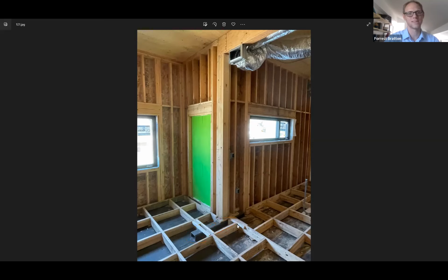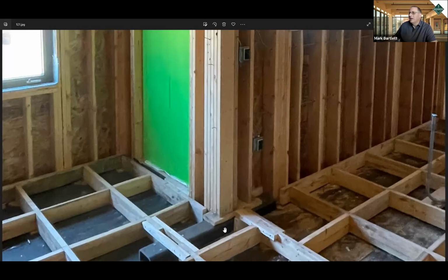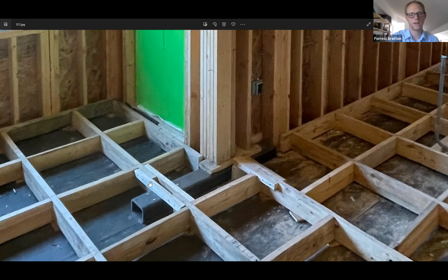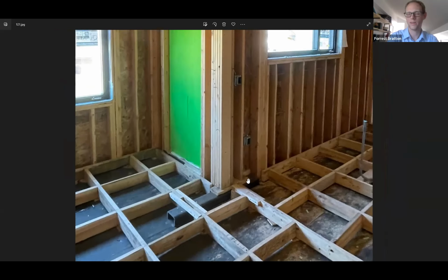We can't do this. One of the things I noticed in this image I've pulled up here, you've got basically a beam spanning across an opening, and obviously a multi-wide column coming down, and then you've got additional steel to distribute that load even further, because trying to put a large point load onto a CLT panel can be challenging. Right. When they're really designed for a uniform load. Right. And we had these in, I think, 8 places.